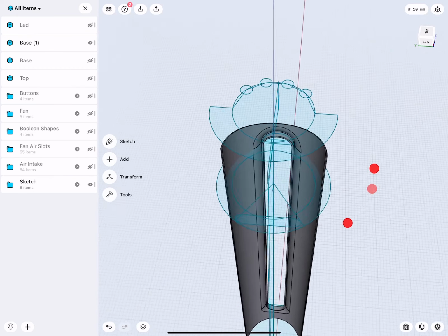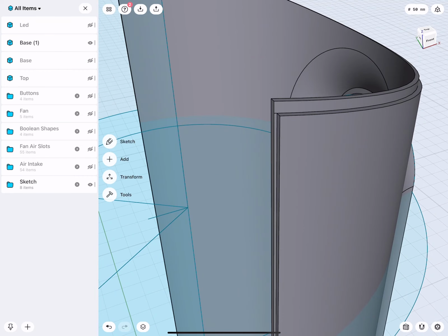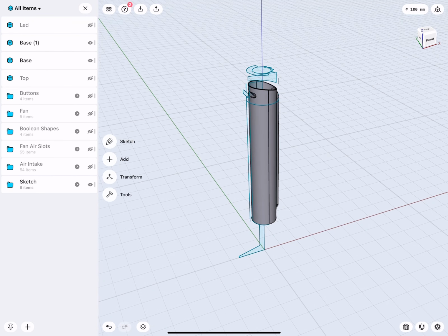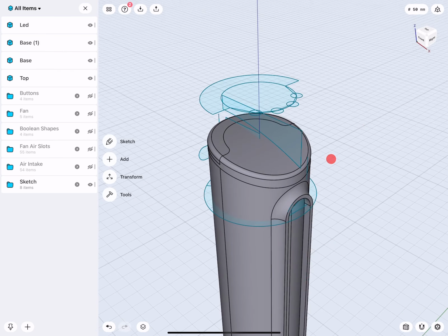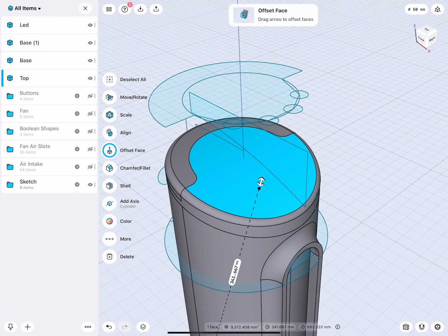And there is now our other lip and groove, the vertical one. So you see that was just simply created by a vertical extrusion of a cutting object and then via the Boolean Subtract, I kind of like split the first design into 2 parts. Super easy. Let's finish this. Here we have our top and there I would like to have 4 buttons in it.